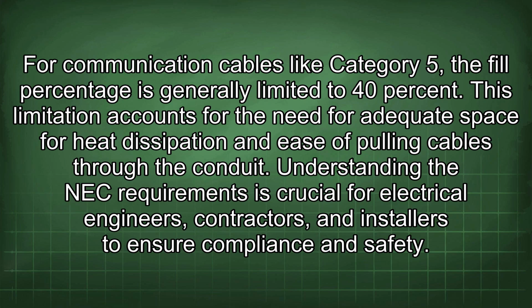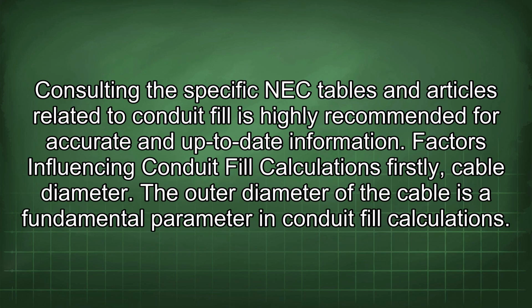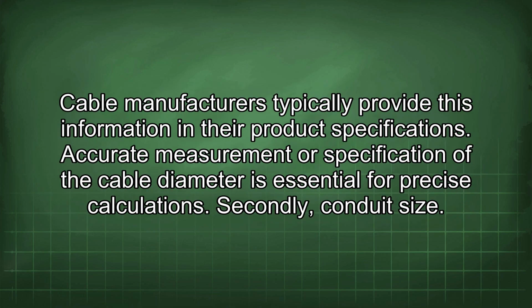Understanding the NEC requirements is crucial for electrical engineers, contractors, and installers to ensure compliance and safety. Consulting the specific NEC tables and articles related to conduit fill is highly recommended for accurate and up-to-date information. Factors influencing conduit fill calculations. Firstly, cable diameter. The outer diameter of the cable is a fundamental parameter in conduit fill calculations. Cable manufacturers typically provide this information in their product specifications. Accurate measurement or specification of the cable diameter is essential for precise calculations.